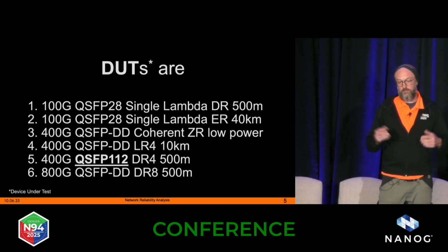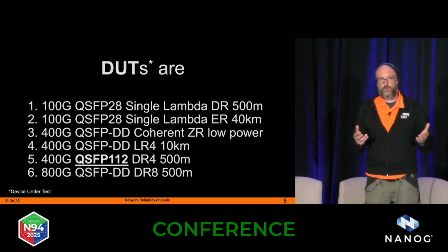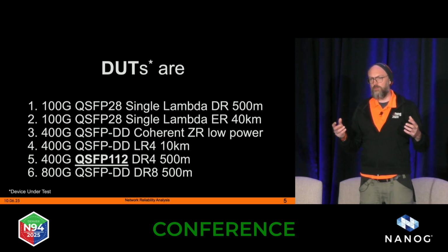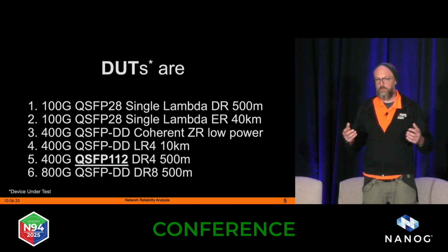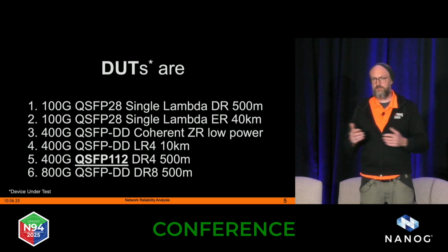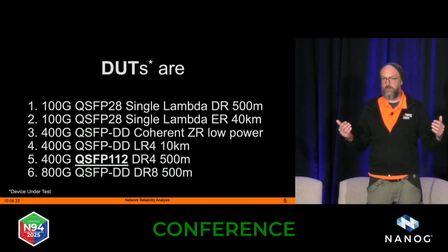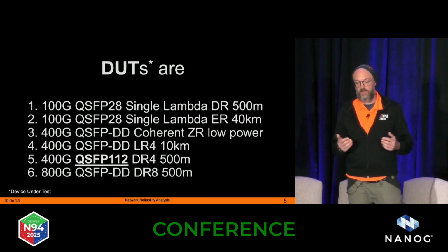And two words about a bit error rate test in general. You might wonder, why is this important? Well, when you bring a link online between your gear, typically people look at the TX and RX levels if they are proper, and then they start looking at layer 2 or layer 3 if everything is set up properly. Is the Ethernet framing fine, and also is my IP setup fine?